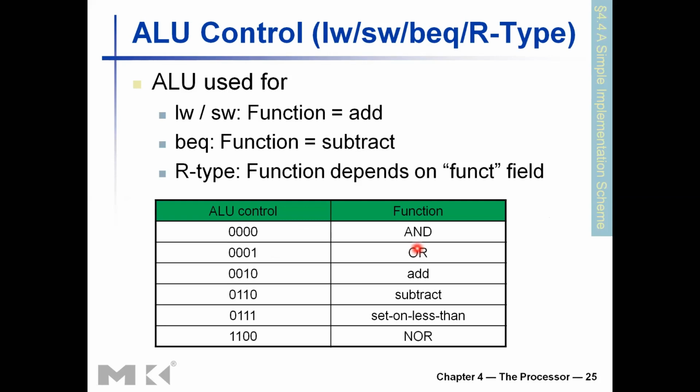Here we are considering only a very small subset of the operations, so not all bits are maximally utilized in this case. You might be able to implement this with even 3 bits if you want. But this is a generic implementation. With these particular ALU control signals, you get that function. So that is how you should implement it if you were to implement the MIPS CPU.